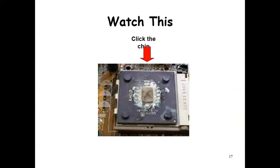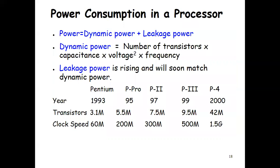It shows what will happen if the power consumption exceeds a particular limit. If there is no heat sink, what happens to the processor? That's what this video shows. And the power consumption is basically calculated based on these two factors. Power is calculated as dynamic power plus leakage power.